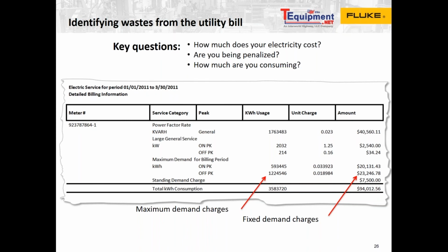So for example, over a 15-minute interval, how much power are you using? They average it out. And if you are above that average, then you have gone beyond your peak demand with that utility and you will be charged a fee for that. I think, I don't want to say for sure, but I think our facility is averaged out over a 15-minute time span. And then to give you an example, other countries might average out over a 10-minute time span. So it really just varies. You got to read your utility bill.